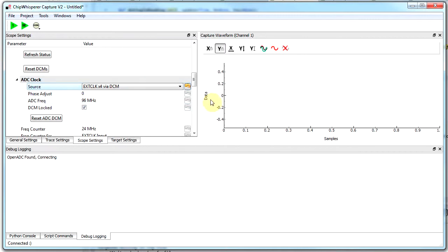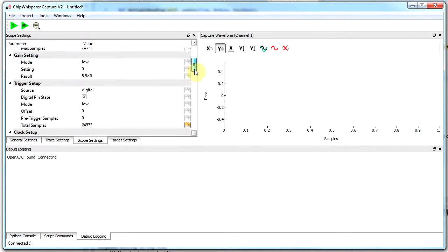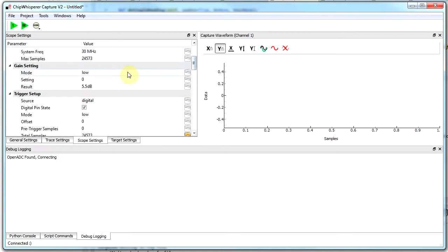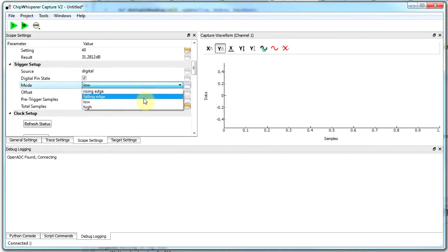It's important to note this 24 megahertz clock is not the AES clock, so this is not the clock you would normally use for sampling. I'm solely doing this because I want to demonstrate how the length of the power signature is changing, just to show you that the speed of the AES itself is being adjusted.